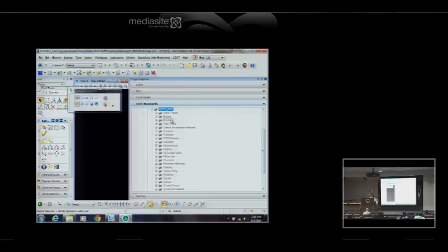are listed here. So actually, if you look at the actual code names here, these aren't really the code names. This is the feature name. Feature gets the code from the SMD, and I prepended it with survey for all these. I did that specifically just in case there was a duplicate name between existing and proposed stuff, like maybe there's a proposed CBR in the catch basin stuff. So feature itself is prepended with the name survey.